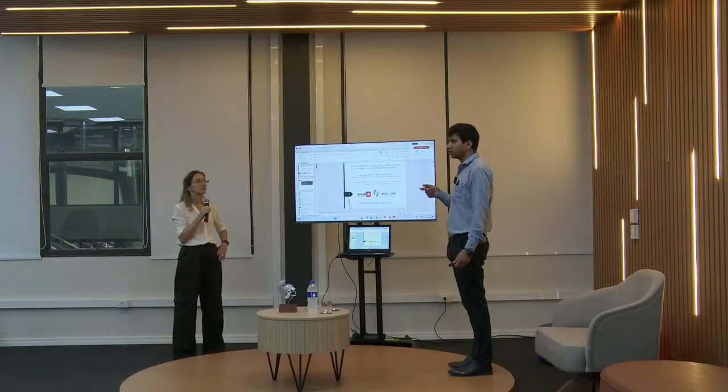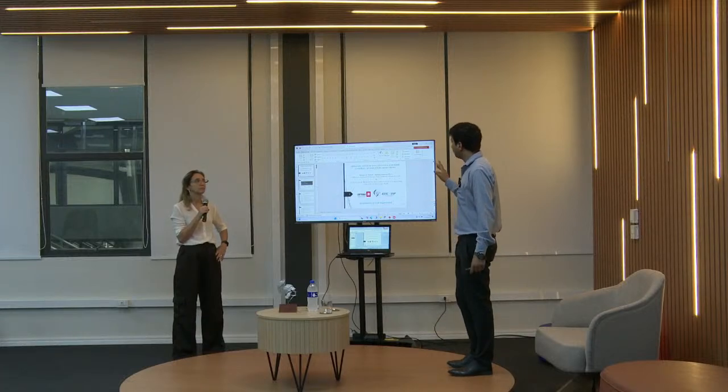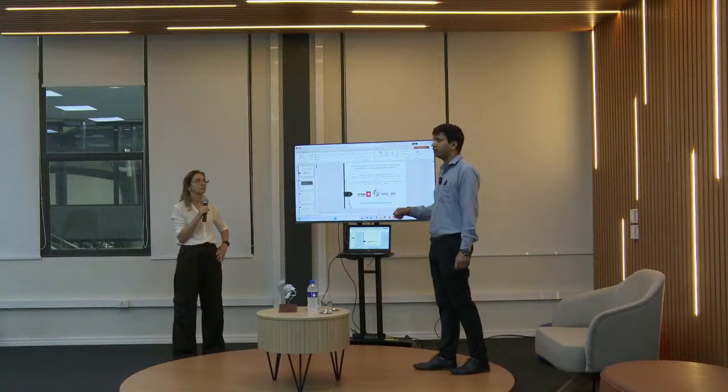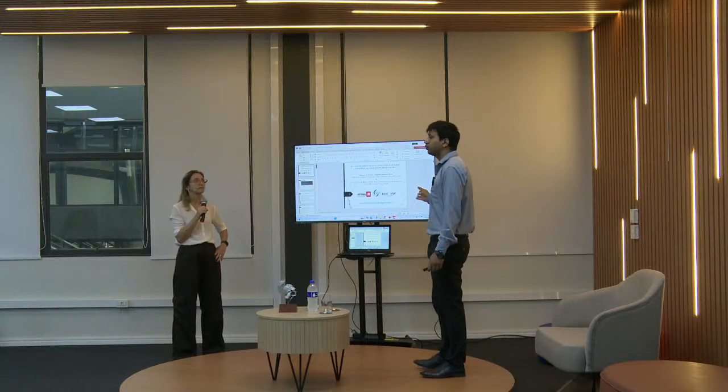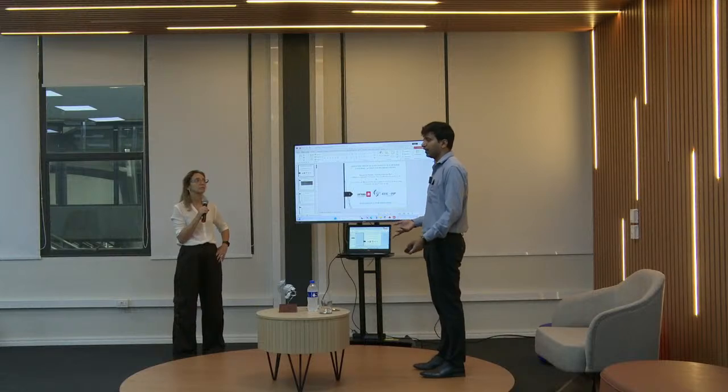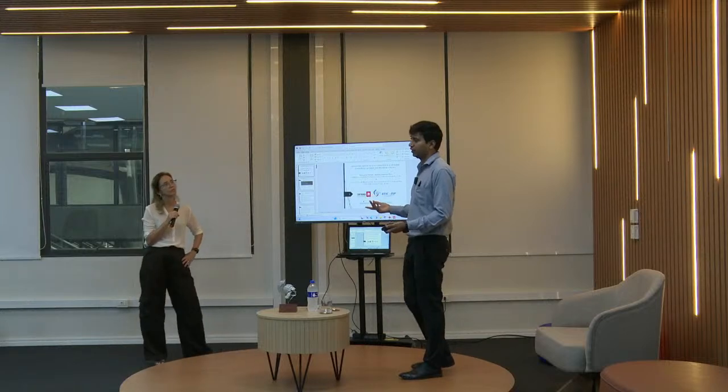Thank you, Leticia. You think this solution has less disturbance compared to the conventional soil nail? Yes. And also, for conventional soil nail we require pressure grouting with controlled pressure. But if we are using helical soil nail, without injection, because it provides enough resistance, you can save the cost of cement also.